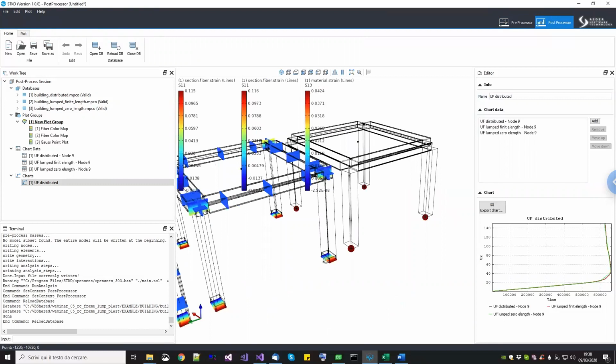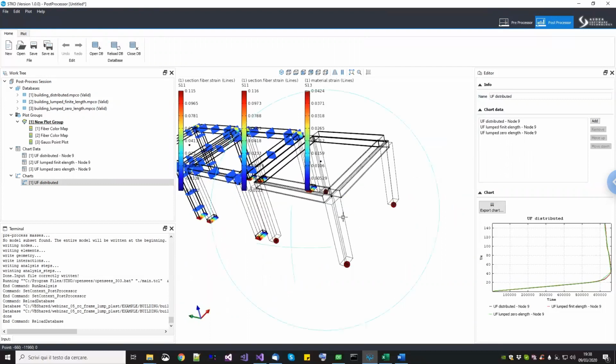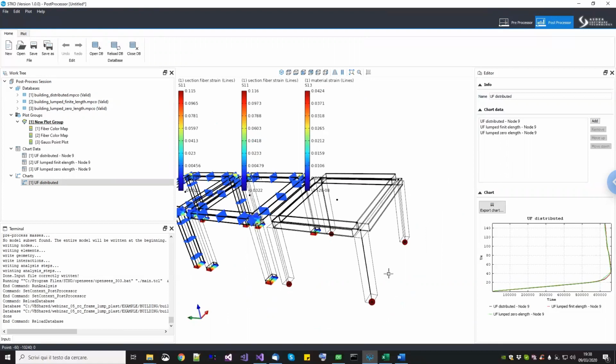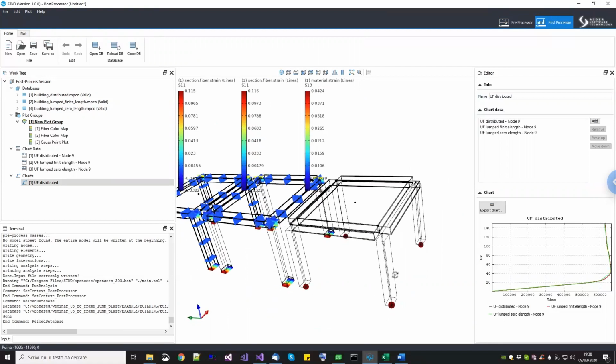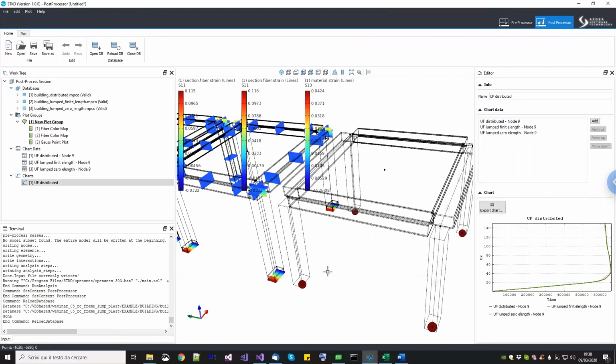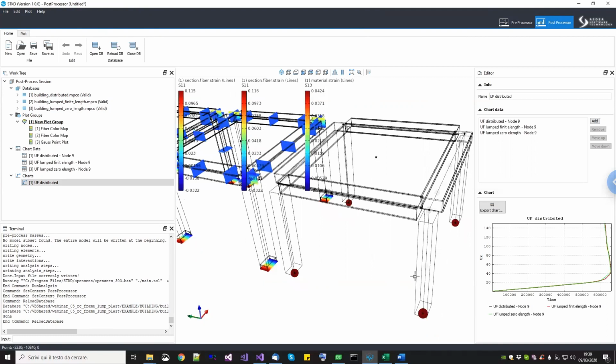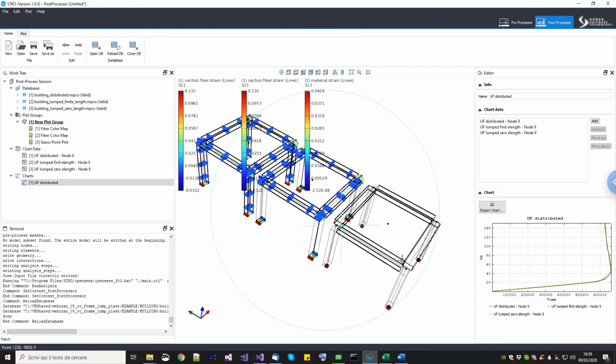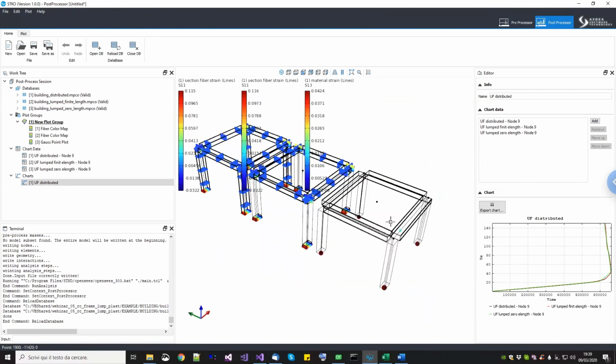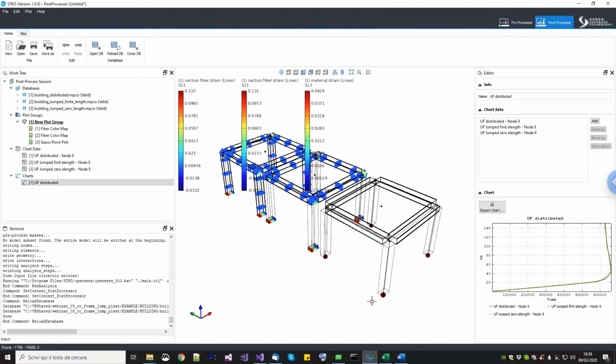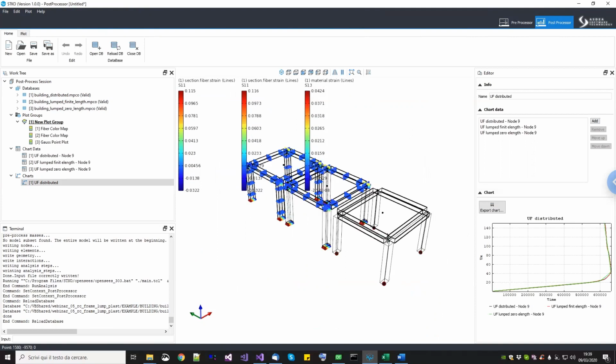But of course, the lump plasticity with phenomenological springs are even faster, but they don't take into account any coupling, either between the bending responses and neither between the bending and axial response. So of course you need to use this one if you need very performant analysis, because you have to do a quite large model, and if you think that there will be no coupling between bending and axial stresses. For example, when you expect axial stresses not to change too much during the analysis.